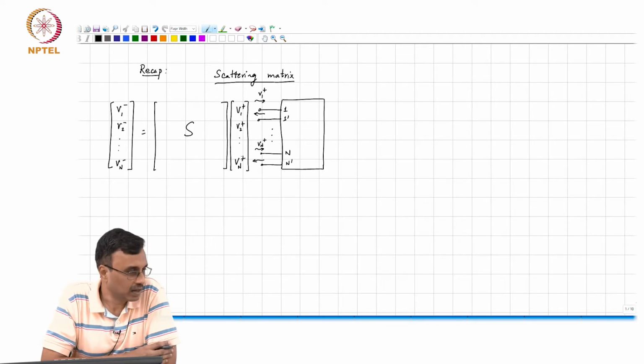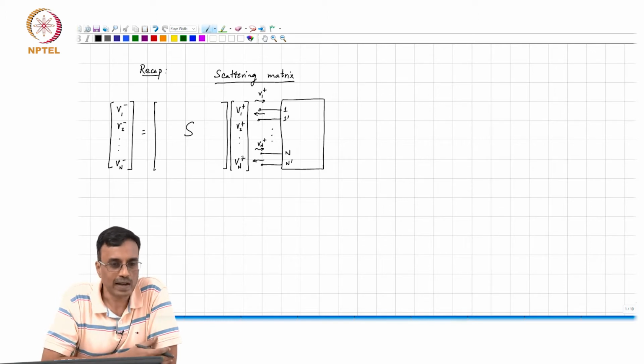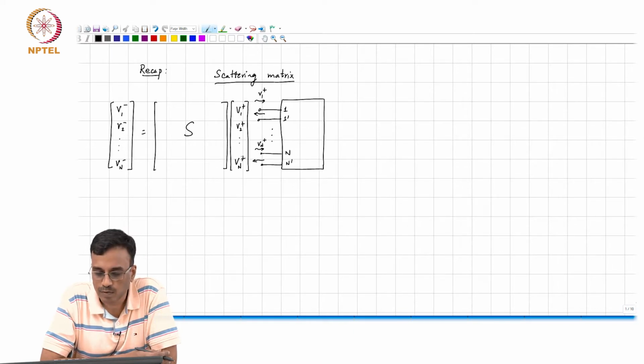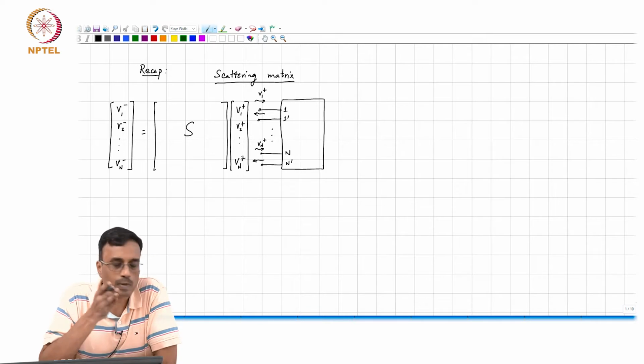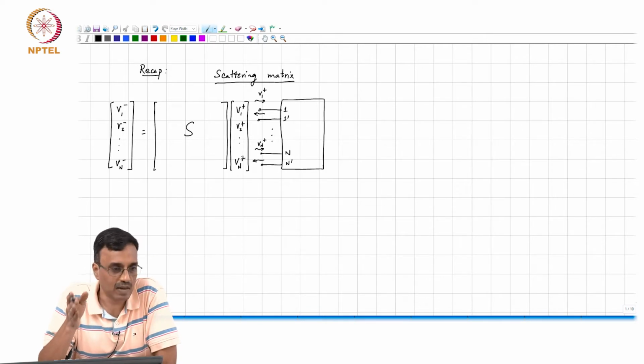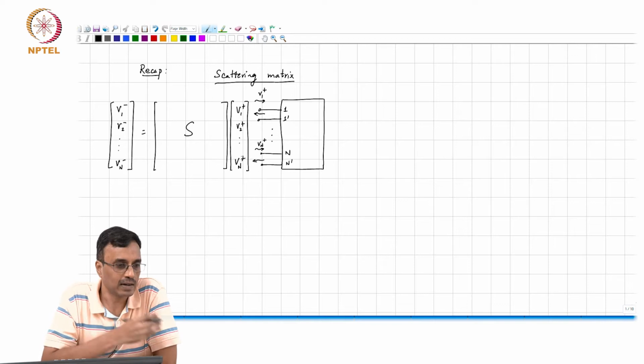And we saw that there is a need for these scattering parameters, right, and the need is motivated by practical realities. When you want to measure admittance parameters or impedance parameters of an N port, and most commonly a 2 port, one has to terminate the port with either an open circuit or a short circuit, and of course, in reality it means that you will not be able to place the short exactly at the boundary of the port. You will have to connect it through a cable.